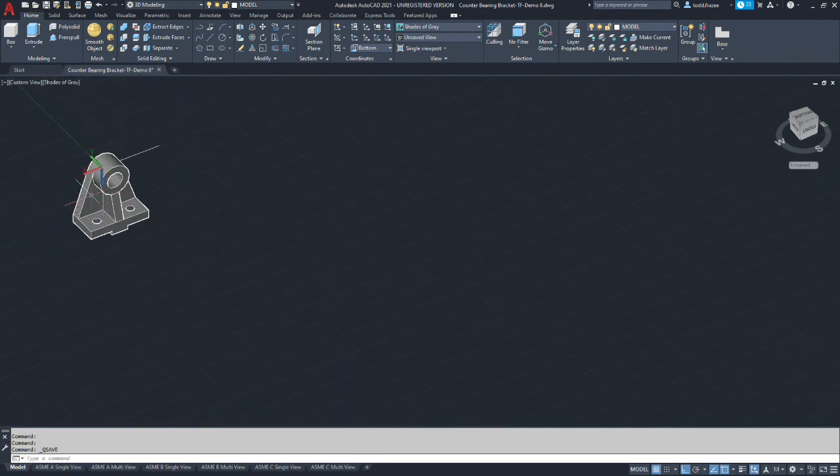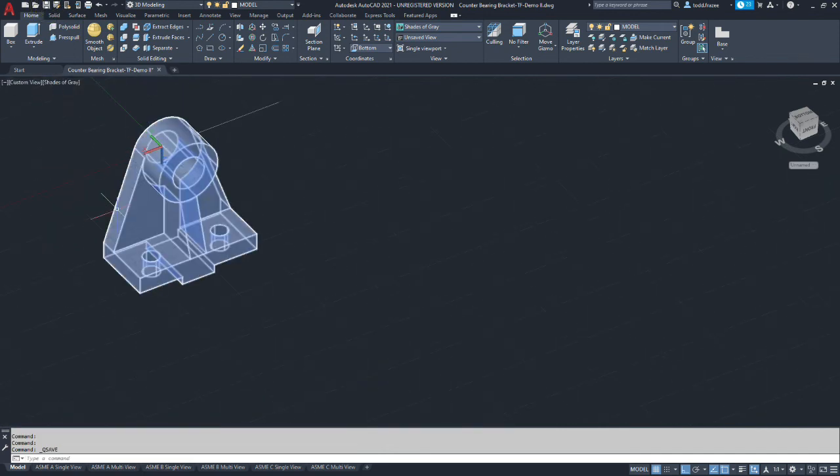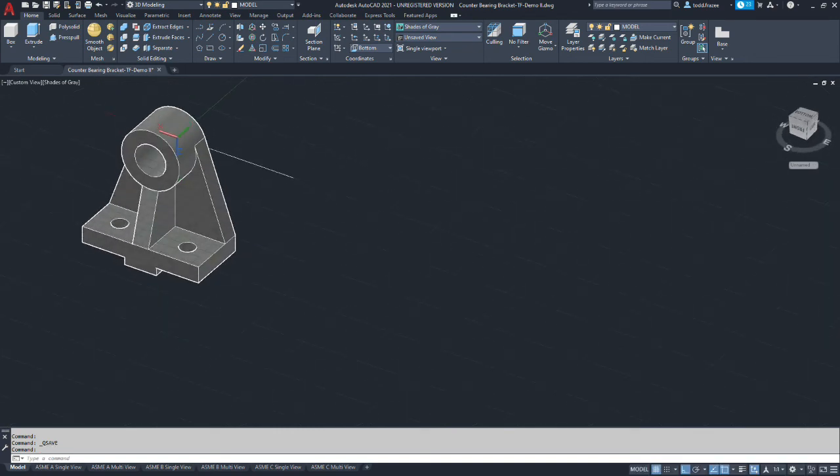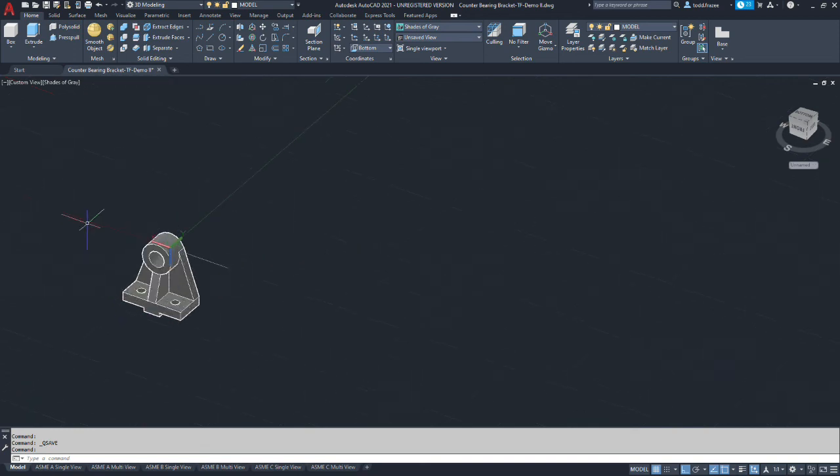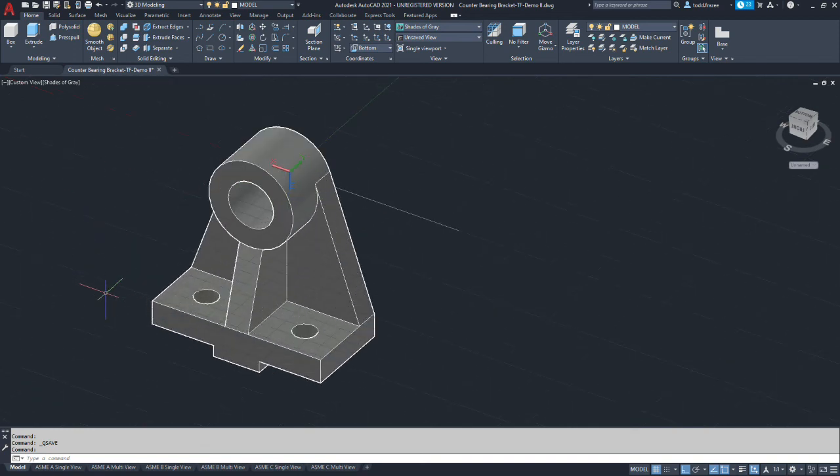Okay, this completes all the steps for the additive processes, and I suggest you get to this stage before you attempt filleting. Once your fillets are going in, it's hard to come back and change your main features. So at this point, you might want to check your work, make sure everything's dimensionally correct, and then move on with fillets.